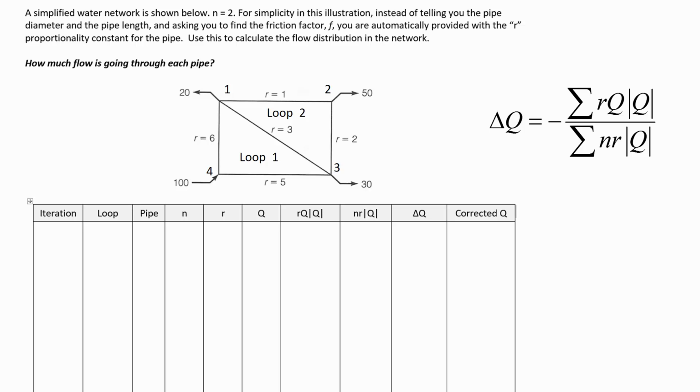We've got coming in 55, going out 55. So continuity works, all right? And it's not coincidence. As long as you make a correct split at each step, then that last one will just miraculously end up where it needs to be. But just to emphasize again, this isn't the only correct flow balance that you could use in your first iteration. It could literally be anything.